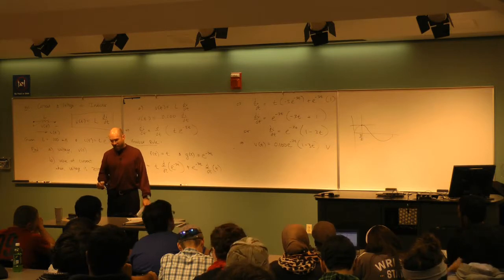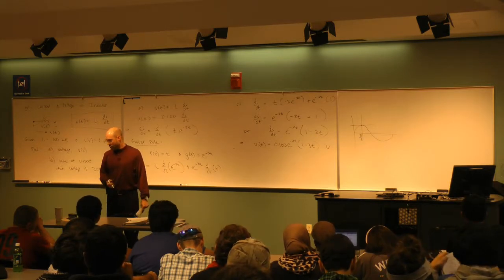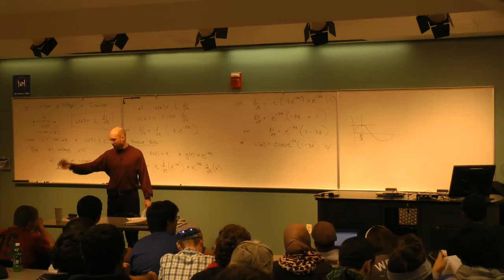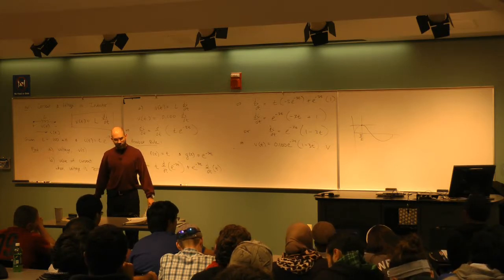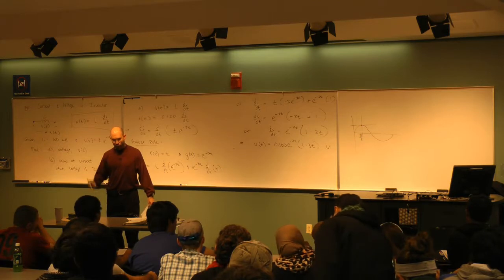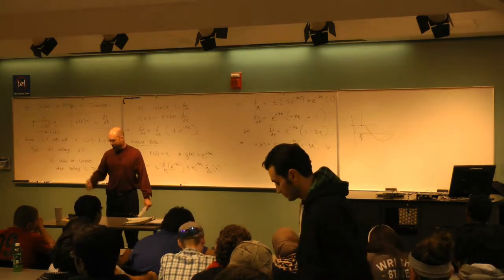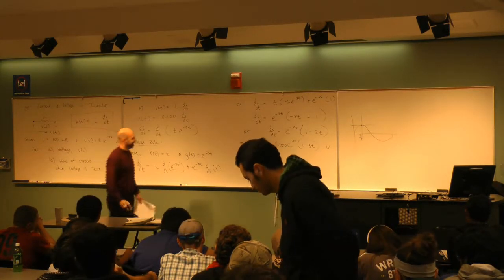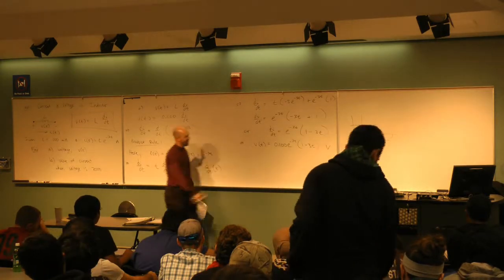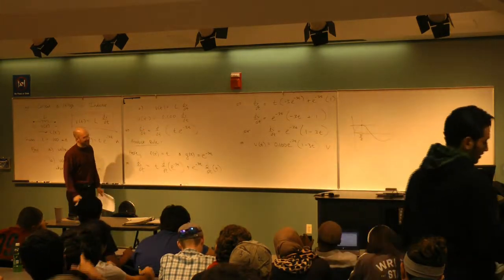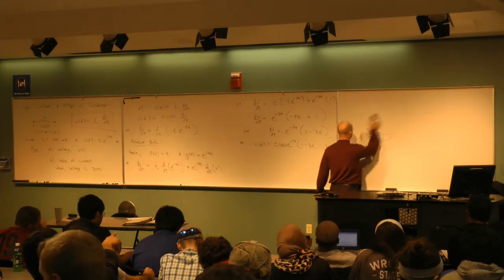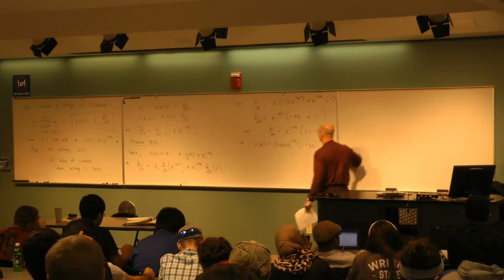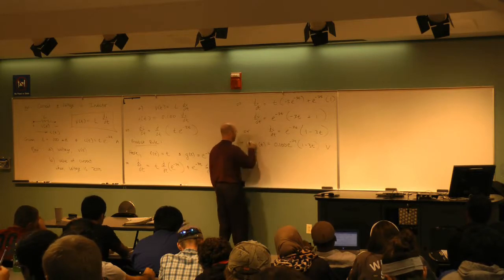If you screw that up, you could be talking about the difference between milliamps and amps. And what's the difference to you if you grab hold of a wire and it has either milliamps or amps? Life or death. So it's pretty important in circuits to get your units and orders of magnitude straightened out. But if you leave everything in base units, this is just going to be volts here at the end.